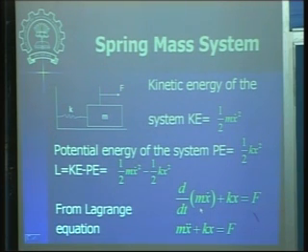Now q dot in this case is x dot, so you differentiate this partially with respect to x dot, and then you will get this m x dot here. So d by dt of m x dot minus, you differentiate this term again, because you see that you are taking here dou L by dou x, and potential energy is only dependent on x. Kinetic energy is independent of x. So you will take only this term in this part of the equation, which is dou L by dou x. Okay, so you get this k x, and that is equal to F, which is a force applied in the direction of x.